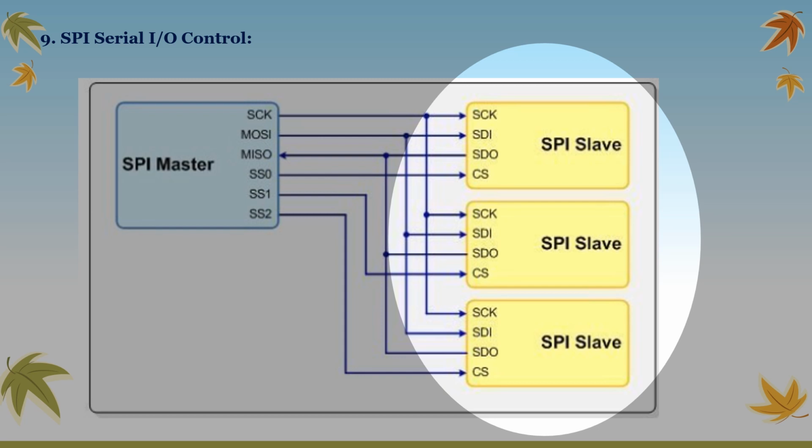One unique benefit of SPI is the fact that data can be transferred without interruption. Any number of bits can be sent or received in a continuous stream. With I2C and UART, data is sent in packets, limited to a specific number of bits. Start and stop conditions define the beginning and end of each packet, so the data is interrupted during transmission.